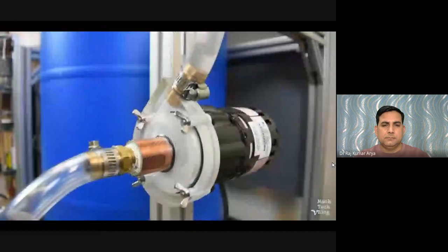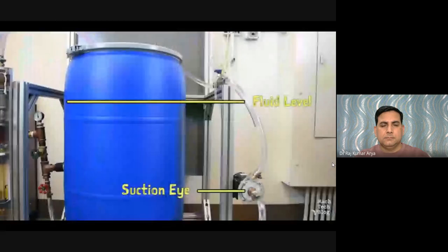It's important to add that because of the way that centrifugal pumps impart energy to fluid, the impeller must always be fully submerged and in direct contact with the pumped fluid. As we can see from this little light-duty pump, a centrifugal pump will not pump air, and it will not suck fluid through piping like a straw. So before the pump is turned on, the casing must be flooded with fluid, a process known as priming. And during operation, there must be a sufficient amount of available fluid under positive pressure at the suction inlet of the pump to replace the fluid which is being discharged. This is usually accomplished by placing the pump below the fluid level of the source tank.